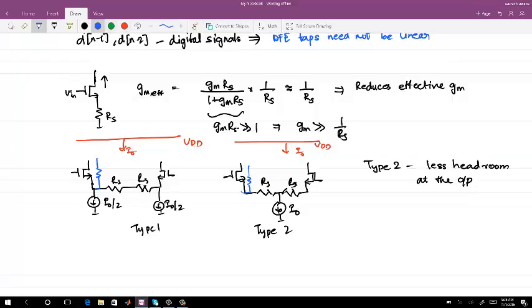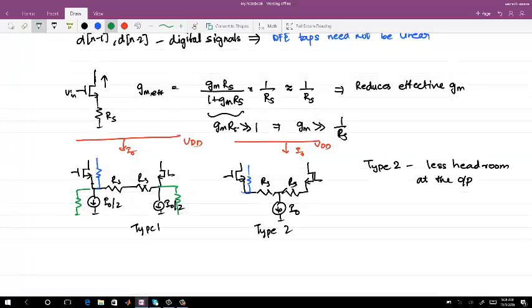Bias, yeah. So for the bias, GDS will be there, but this is another point, but normally the current source is GDS. You design the current source such that they are not affected by the channel length modulation. That means your GDS is actually pretty low so that your output impedance is high. But surely that point is there. What else?